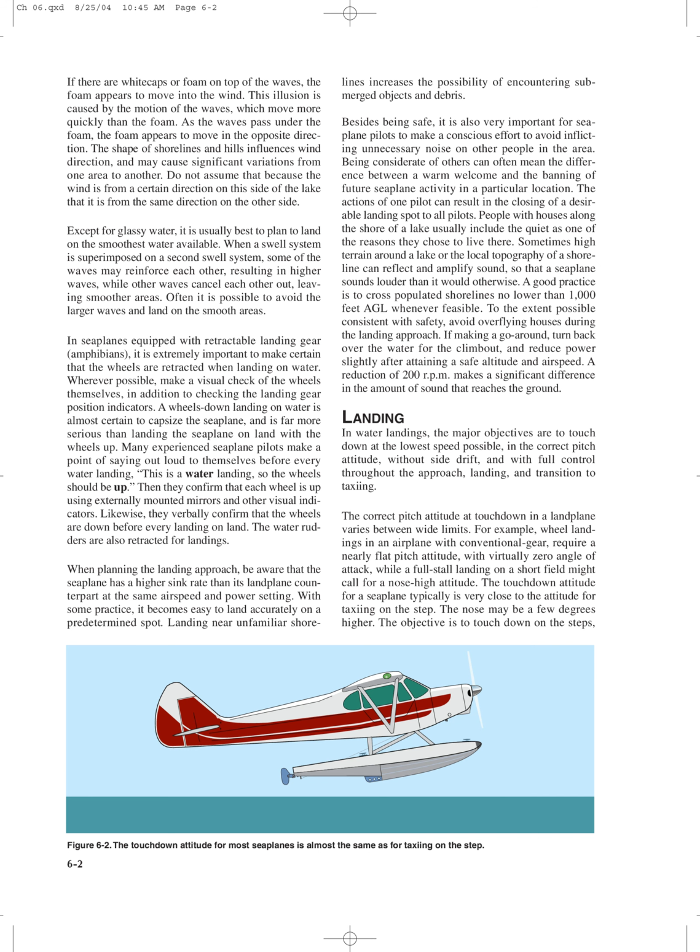Many experienced seaplane pilots make a point of saying out loud to themselves before every water landing, "This is a water landing, so the wheels should be up." Then they confirm that each wheel is up using externally mounted mirrors and other visual indicators. Likewise, they verbally confirm that the wheels are down before every landing on land. The water rudders are also retracted for landings.